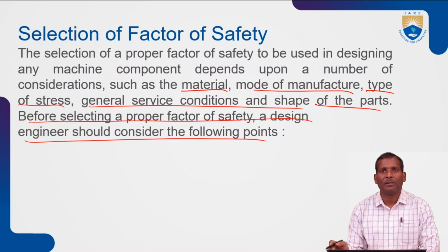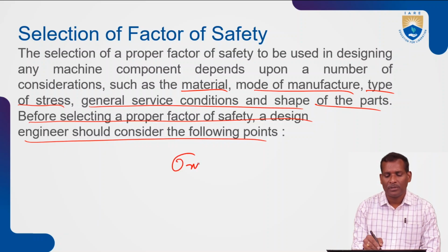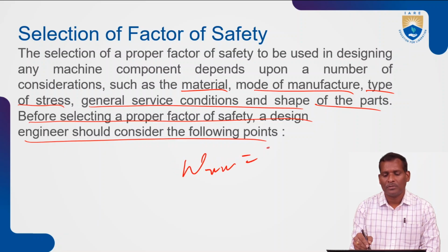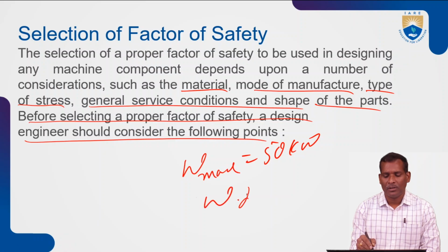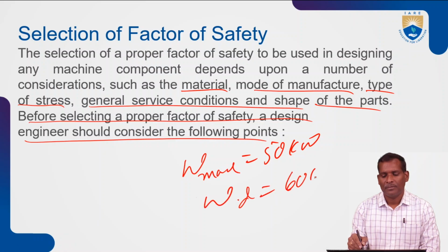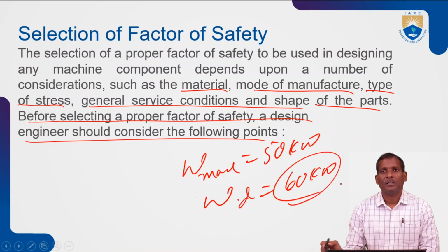If the factor of safety is not selected properly, suppose in the example I told you, he has taken less than 1. Suppose the maximum load is 50 kilonewtons, but the working load or design load is 60. That is wrong.